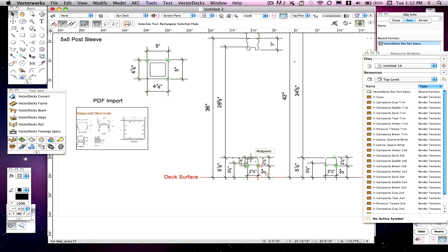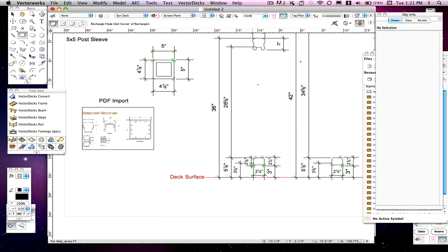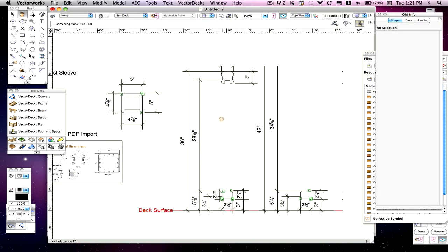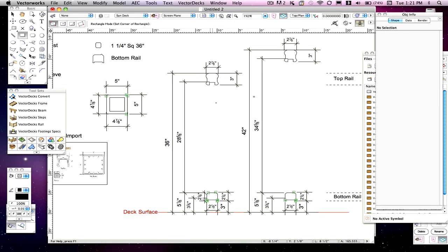So if you notice here, you do have a little bit of room inside here to make the baluster slightly longer. So I first measured the actual distance, and I see it's 28 5/8. I've got a little room in here to extend that baluster. That way, this baluster that you create may work on other different types of top rails and bottom rails, and if you lower that below 3 inches, it'll still work. But it'll definitely work on this particular style because it's coming all from the same manufacturer.